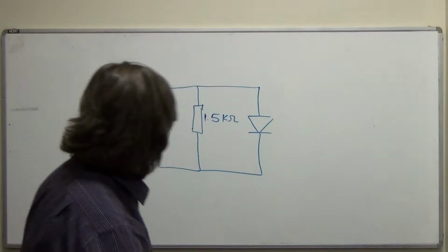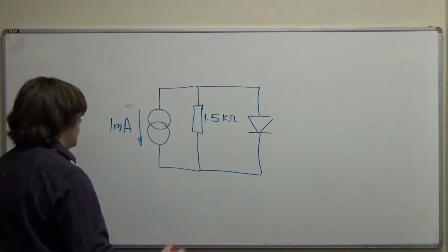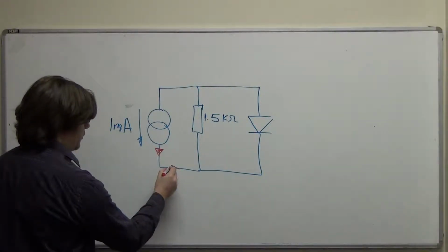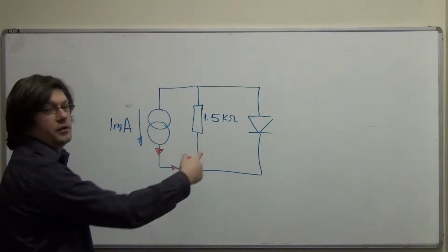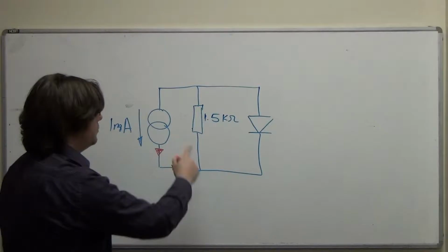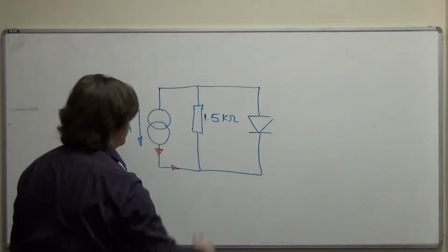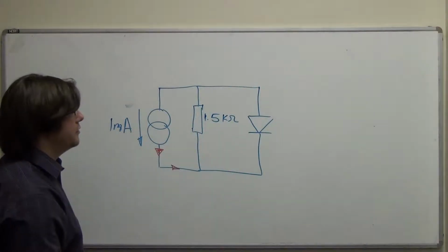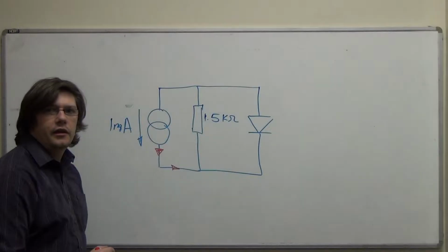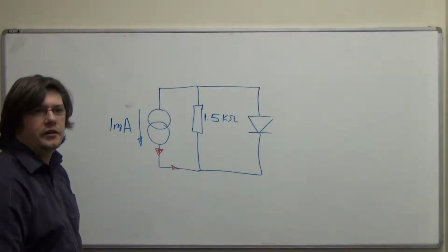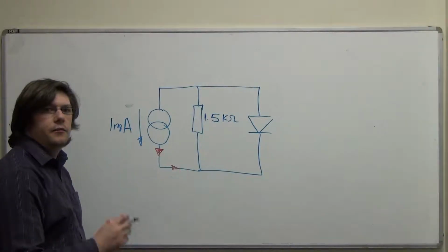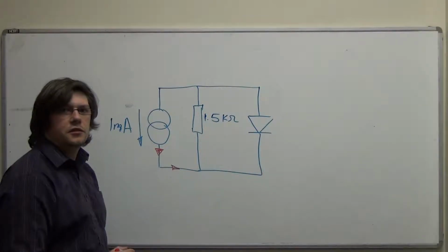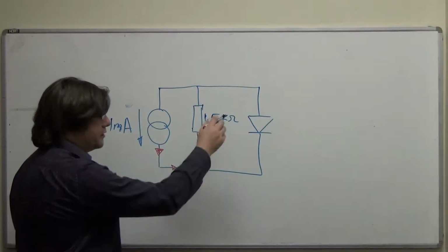So we know that the current's going to have to be going this way, and that it will be going down there, and the current's going to be shared out potentially, possibly, between these two branches, the resistor and the diode. Now, the resistor's quite happy with current in any direction, it's not too bothered, but the diode gets very sad about current the wrong way. It doesn't want to let any current through if it's reverse biased, so we'll have to decide what's going to happen. If we assume that the diode's open circuit for a bit, so we'll take the diode away